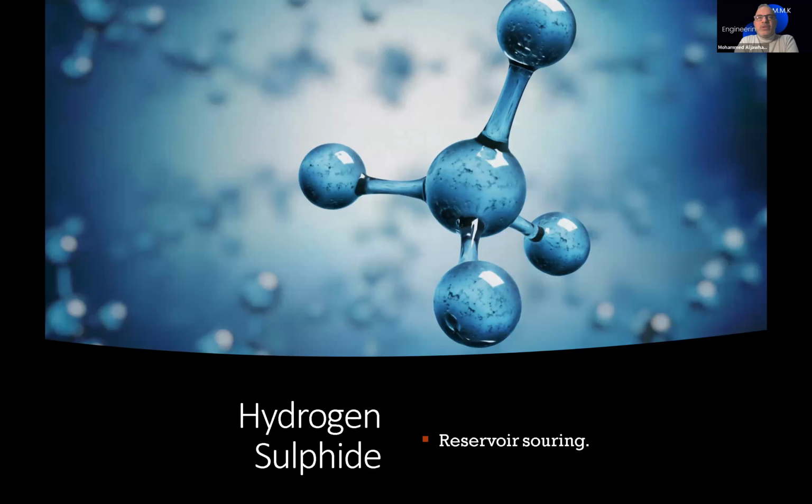The first thing is to investigate the well parameters, I mean upstream and downstream pressure and temperature, taking water samples and having experienced people analyze the chlorides and fingerprints of any kind of sulfate or carbonate inside our wellbore.